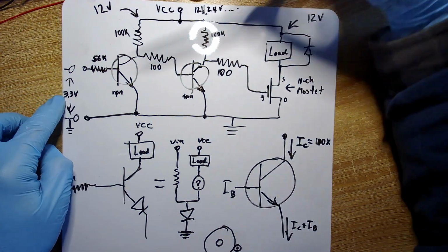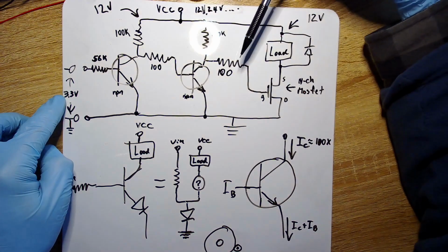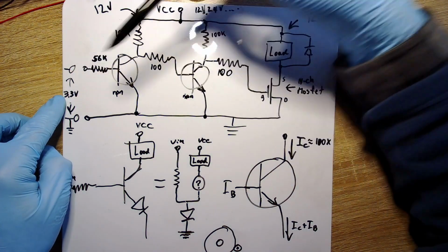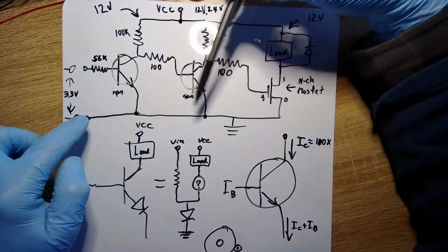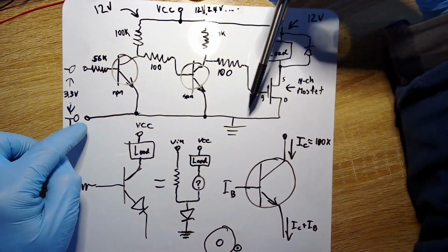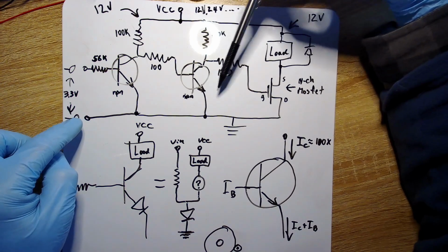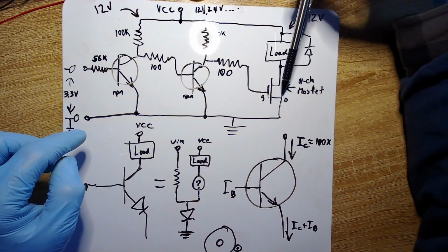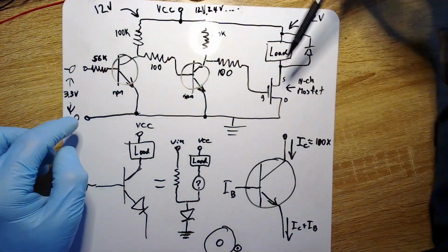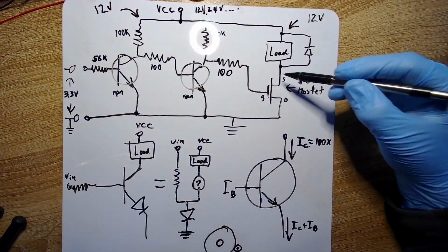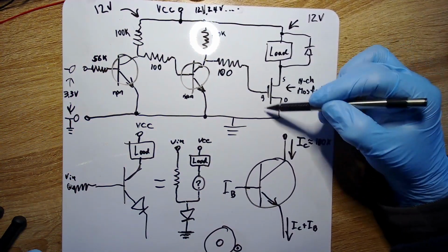You bring 3.3 volts when it's high. So when this is 3.3 volts, this is going to be 12 volts, right? And when it's 0, it's 0. And that's the common emitter, right? See how everything's common to the emitter? The emitter is common. Although this is not an emitter, it's a drain, it's still where the current's coming out. So the current is going into all of these. And essentially this is just a switch, right? This is just where we connect.